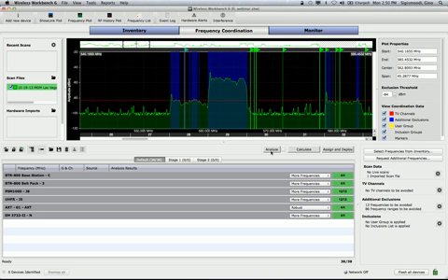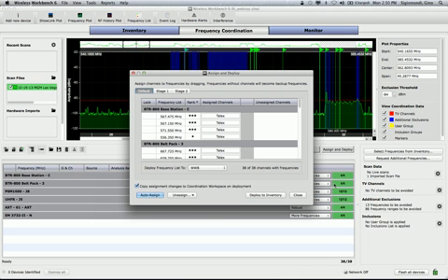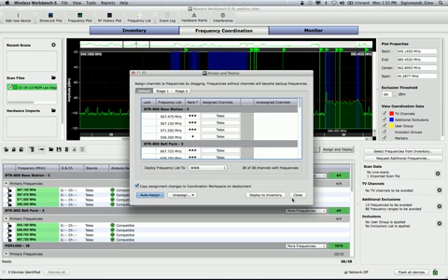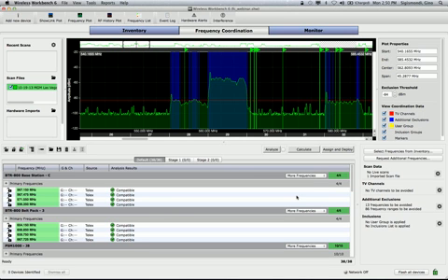The one thing I want to call out before we depart from this view is that when it comes to Shure networked wireless gear, particularly some of the newer stuff, this becomes so much more convenient. Instead of generating a report that someone has to use to manually tune receivers and transmitters to the specific frequencies, users can assign and deploy all of their coordinated frequencies directly to the gear. So that step of tuning devices to the proper frequency is now a push of a button, and their assignments can even be tweaked manually if they wanted to. It's that simple. So that's a little glimpse of how frequency coordination can be alleviated by the application. Great. Thank you very much.